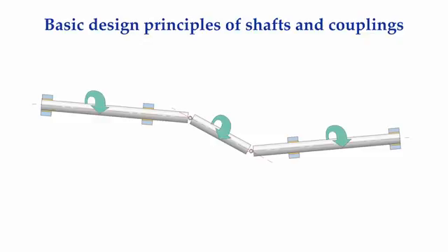The flexing points on each end of the coupling must have the capability to transmit the torque from one shaft to the other, and we would like the rotation to be smooth and in some cases be capable of transmitting tremendous amounts of power. If you remember from the introductory tutorial, a shaft running at 1800 RPM will rotate 2.5 million revolutions in a day, which is 78 million revolutions in a month, and just shy of 1 billion revolutions in a year.